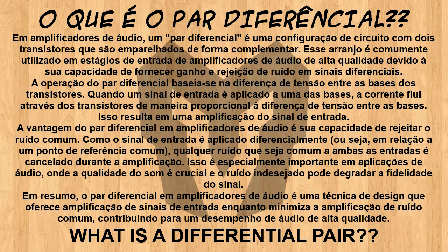The advantage of the differential pair in audio amplifiers is its ability to reject common noise, because the input signal is applied differentially, i.e., relative to a common reference point. Any noise that is common to both inputs is cancelled during amplification. This is especially important in audio applications, where sound quality is crucial and unwanted noise can degrade signal fidelity. In summary, differential pair in audio amplifiers is a design technique that provides amplification of input signals while minimizing amplification of common noise, contributing to high-quality audio performance.